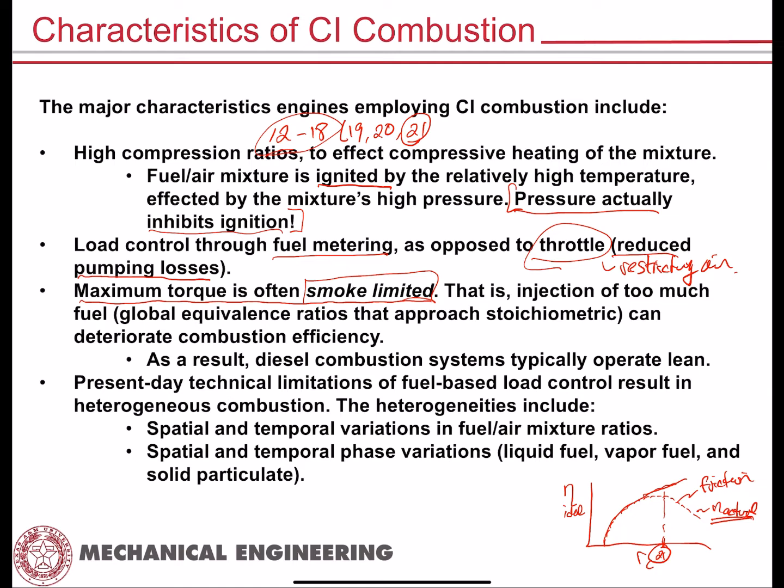Okay, so how does this all relate to smoke limitation? Well, now imagine that you're running the engine and you're trying to produce torque. So you're injecting a certain amount of fuel into the cylinder. And let's just suppose for a moment that that fuel that you're injecting into the cylinder creates an equivalence ratio of, say, 0.6 in the cylinder, right? Overall lean, okay? Fuel-air equivalence ratio of 0.6. Now, that gives you a certain amount of torque. You want to make more torque.